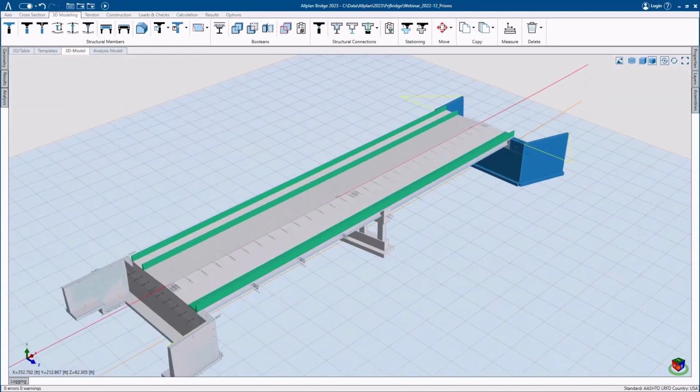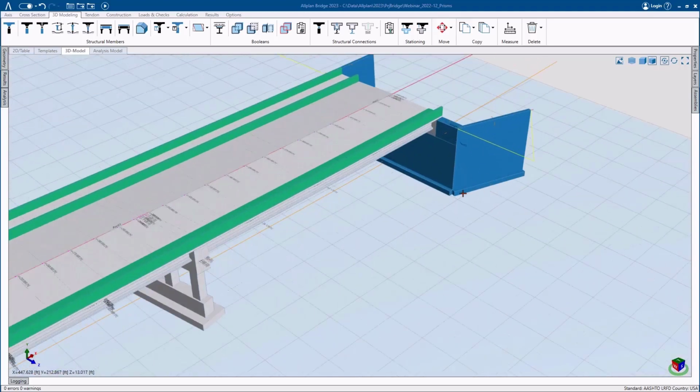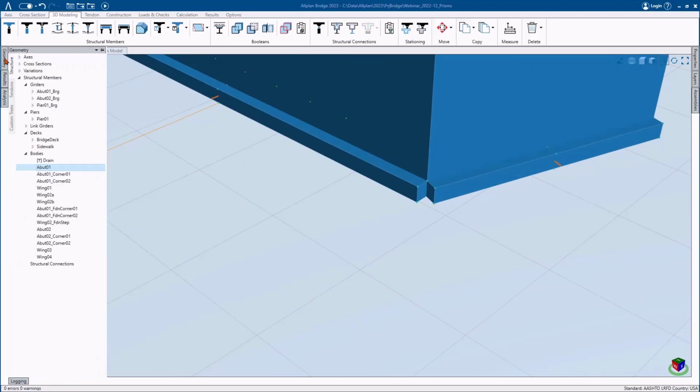All right. Now we can see we've got most of the primary prisms within the model already. There's a few little interfaces though that we're going to want to clean up before going further. Let's finish up the model of the abutment by including some additional bodies to model the chamfer at the location where the abutment wall meets the retaining wall, and then the gap that is currently appearing at their respective footings.